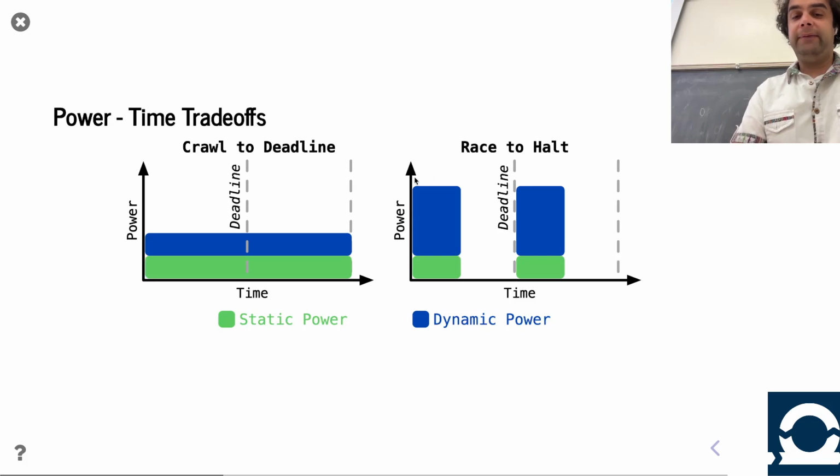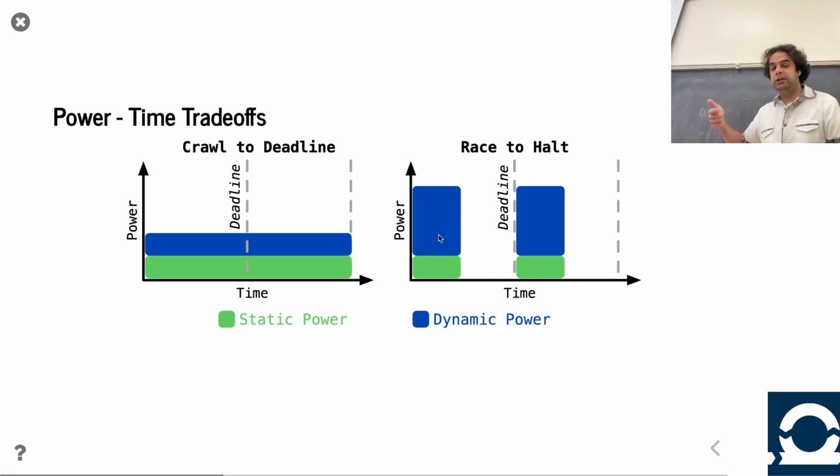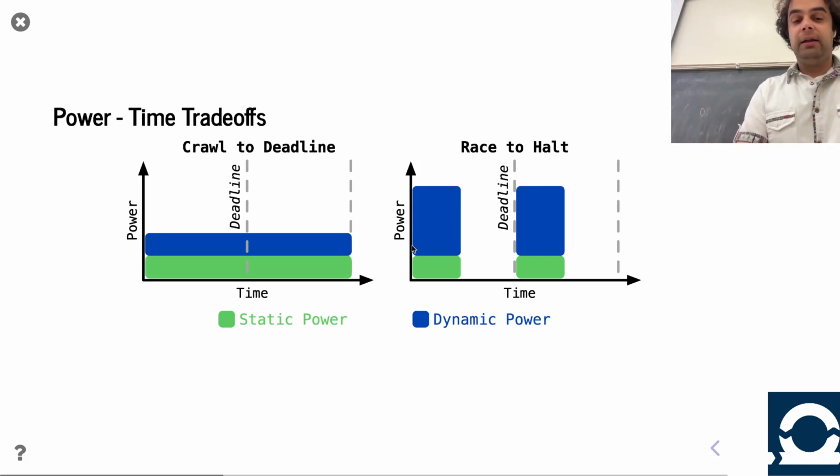Now, the price of going fast is that you burn dynamic power, right? And like I said, you increase the voltage, you increase the frequency, you crank it. That's going to require more power. So, of course, the question is, which one's less energy, right? You're comparing the extra dynamic energy you paid to go faster. Because in theory, by going slower, you're going to burn not just lower absolute power, but maybe less dynamic energy, because of lower voltage, P = CV²F, right? The V squared, lower the voltage, you get a real benefit.